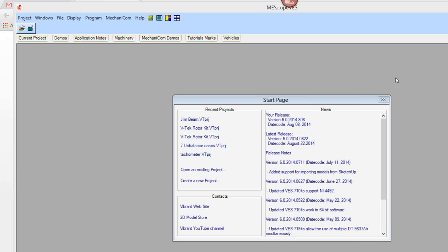Now, an autospectrum, which is a spectrum of a signal, will certainly show us peaks in the spectrum. Those may or may not be due to resonances, because we're just measuring response, and we're not dividing out the spectrum of the force as an FRF does. So if we're only measuring responses and we have peaks in the data, we can go ahead and curve fit those peaks and attempt to recover the operational modal, or what are called operating mode shapes. They may or may not be mode shapes.